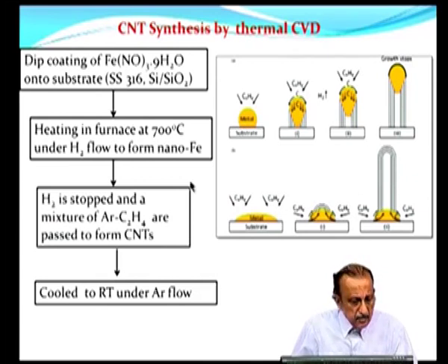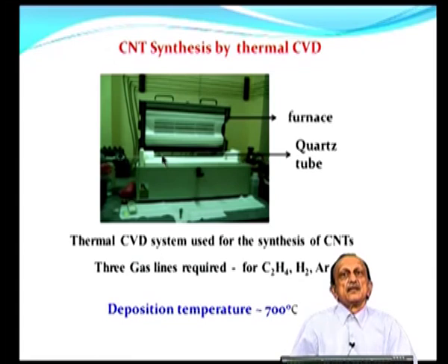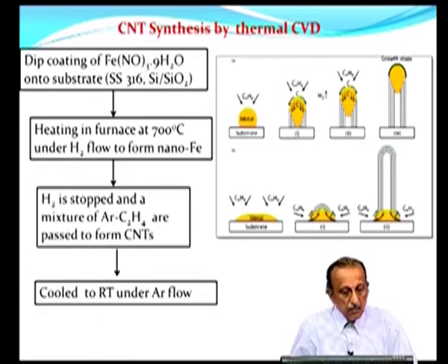It turns out that in such a system one can conduct these reactions under an applied electric field, giving rise to carbon nanotubes that are essentially perpendicular to the substrate. So, you can have a well organized array of carbon nanotubes growing on a silicon substrate by having an applied electric field during the deposition process.